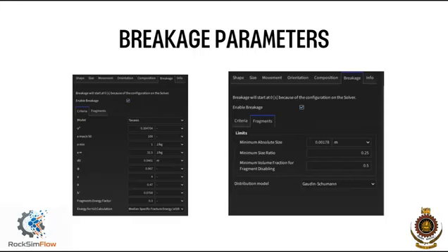Here, we adjust values like toughness, fracture energy, and breakage probability, which control how easily particles split when subjected to compressive forces. Small changes in these parameters can significantly affect final particle size distribution and overall crushing efficiency.